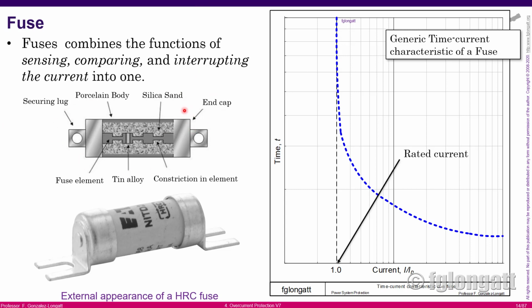Here you can see a cross-section of one of these fuses, which is extremely lovely. You have two terminals. Inside you have the conductor I was talking about, that extremely clever design, and that is what we call the fuse element. Inside the fuse element, there is a very small breaking point.